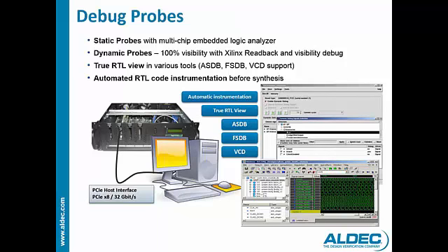With dynamic probes, the signals can be chosen at runtime, whereas static probes are chosen during the setup process. If you want to change static probes, the design has to be resynthesized, but with dynamic probes you don't have to do this; it can be done at runtime.